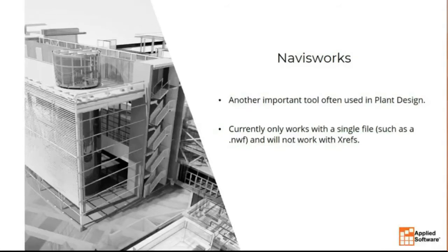Previously with Navisworks, you could just bring in all your drawing files, right? Well, your drawing files are now on a cloud-based web server, so you can't really just throw them on there. Navisworks and BIM 360 have a little bit of an issue with Xrefs. We found workarounds, and we're going to talk about that in a minute.